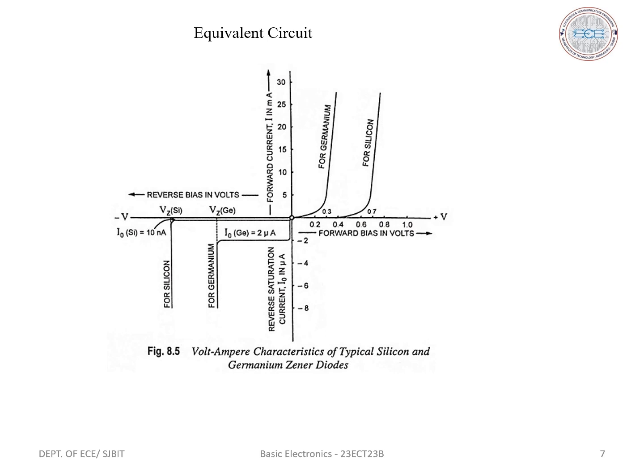Any increase in the source voltage will result in an increase in reverse Zener current. The Zener current after the reverse breakdown must be controlled by connecting a resistor R. This is essential to avoid any damage to the device due to excess heating. After a reverse breakdown, the Zener diode operates in a region called the Zener region.